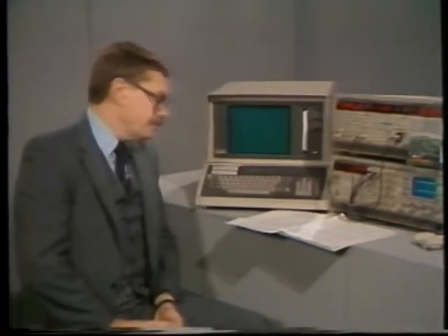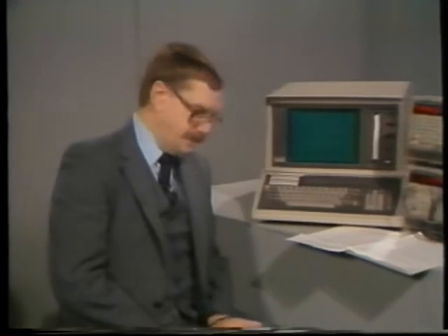Let's take a look at the bus standard itself. First, to straighten out any possible terminology confusions, let's establish for our purposes that HPIB equals GPIB equals IEEE standard 488 with both 1975 and 78 revisions. And in fact, the European IEC standard 629 is functionally identical but uses a different connector.